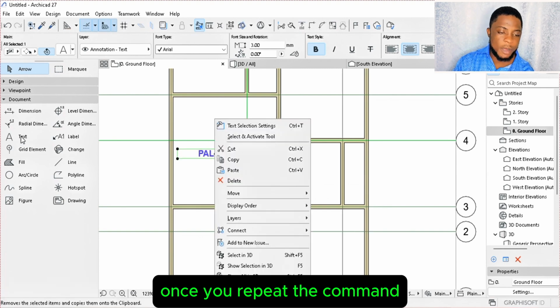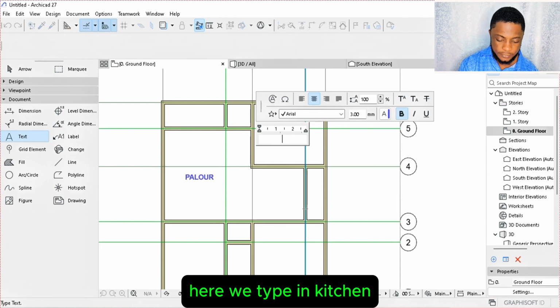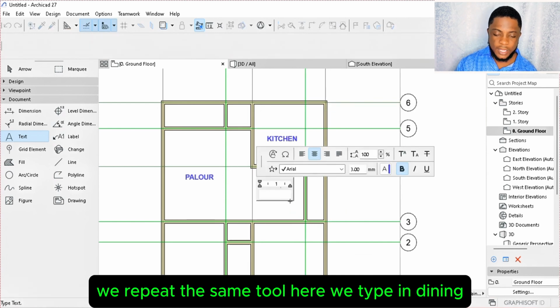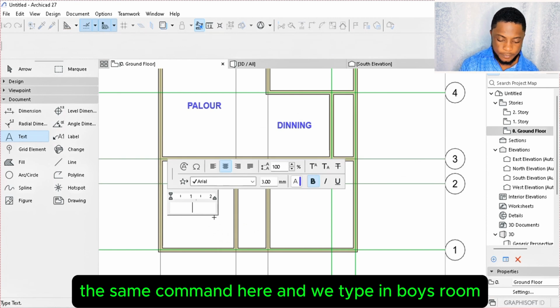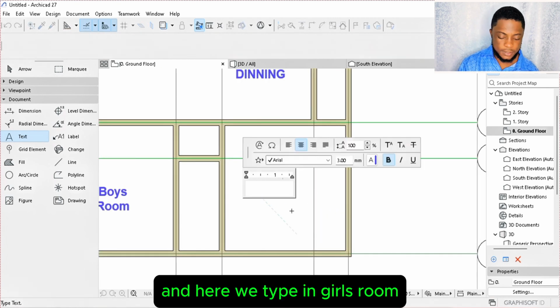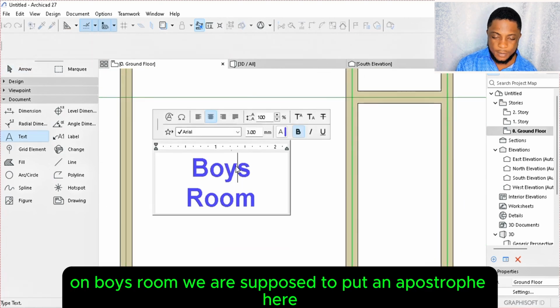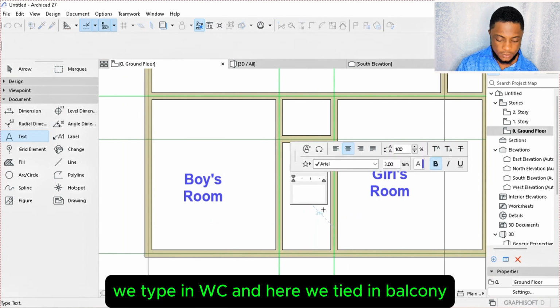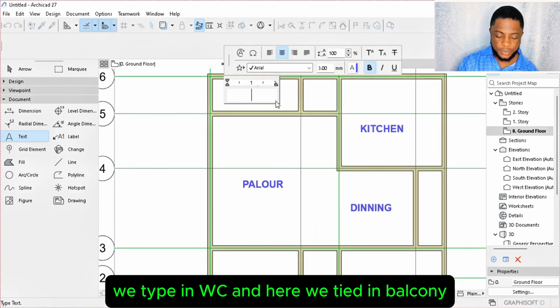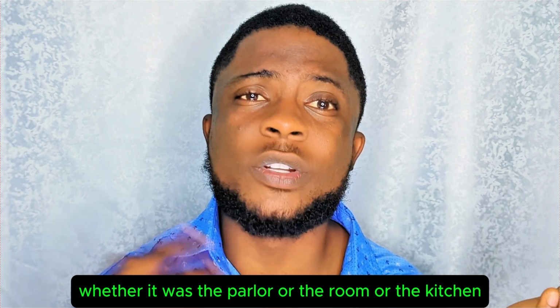I'm going to repeat the command, clicking on text, and we draw a rectangle here. We type in kitchen. We repeat the same tool here. We type in dining, the same command here, and we type in boys room, and here we type in girls room. Oh, we made a mistake on boys room. We are supposed to put an apostrophe here. Then on toilet we type in WC, and here we type in balcony. Then I knew what each space represents, whether it was the parlor or the room or the kitchen.